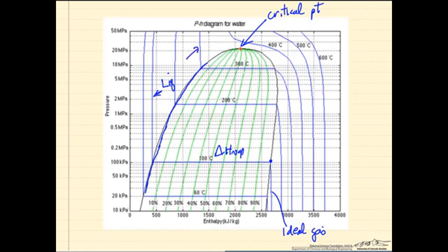So the liquid phase shows behavior that's essentially enthalpy doesn't depend on pressure significantly. We have the phase change at 300 degrees C, but notice now that as we lower the pressure at constant temperature at 300 C, so going along this line, as we lower the pressure, the enthalpy increases. Or the other way, of course, is that at constant temperature, as we raise the pressure, we actually decrease the enthalpy.